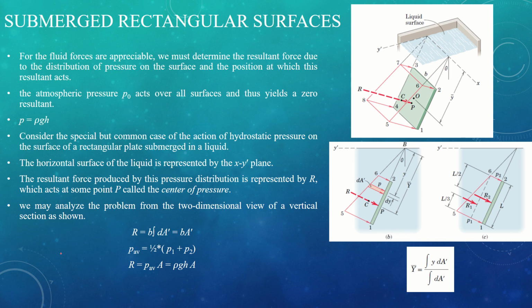Number one, the edge that is closer to the surface would have lower pressure compared to the edges at the depth of the water, because previously we derived an equation that says change in pressure, for a homogeneous fluid of density rho, under the action of gravitational force with g, is directly proportional to the depth, that is delta h. The deeper you go into the water, the more you put your plate into the water, the more pressure at the bottom part will increase and less pressure will be at the top part.